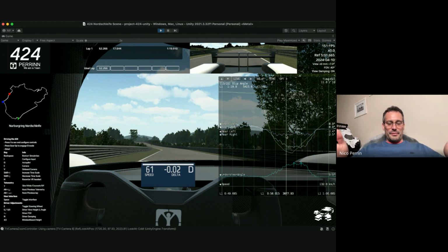As you all know, slip angle is the relative angle of the tire with the velocity of the track, and that's what builds your lateral force. So in the middle of the corner, you're sliding at the maximum slip angle. In fact, if I look at the mid corner here, the front tires are sliding at 8 degrees. The rear tires, 2.6, 2.7.